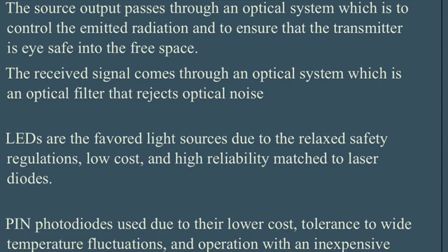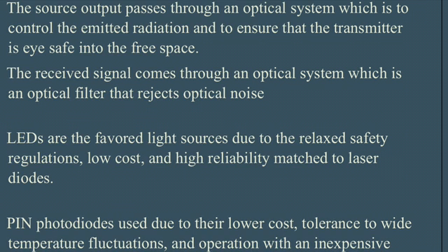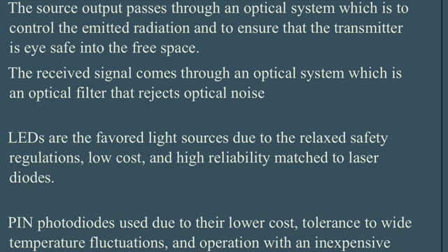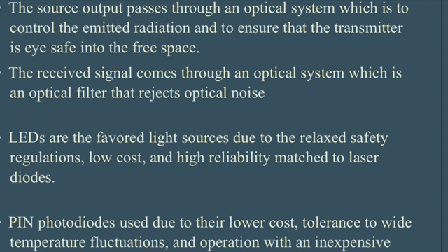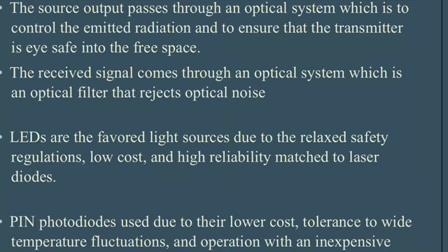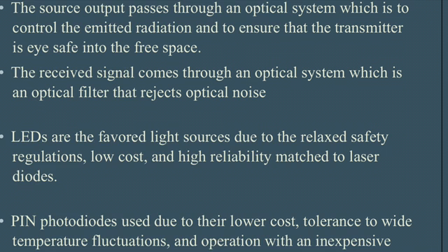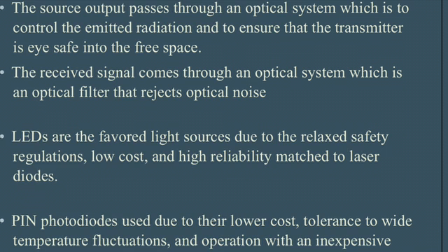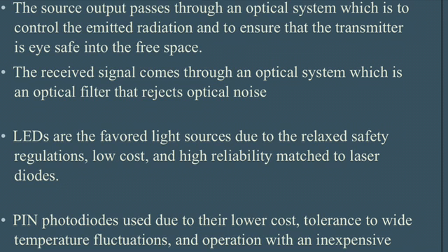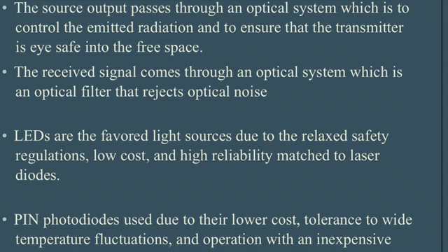LEDs are the favored light source due to the relaxed safety regulation, low cost, and high reliability compared to the laser diode. PIN photodiodes are used due to the lower cost, tolerance to wide temperature fluctuation, and operation with an inexpensive low bias voltage compared to an avalanche photodiode (APD).